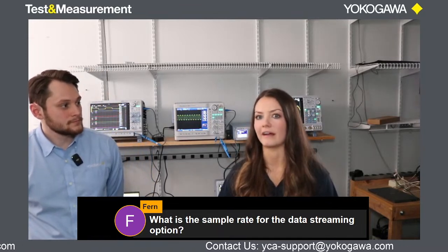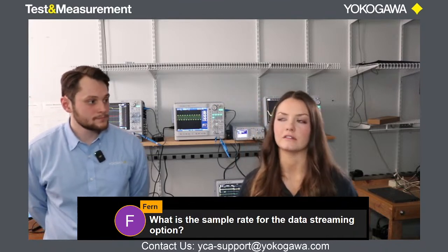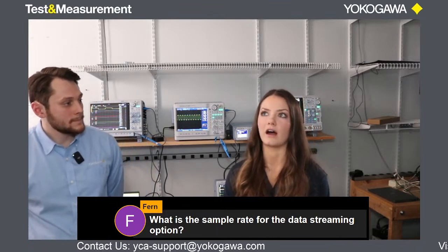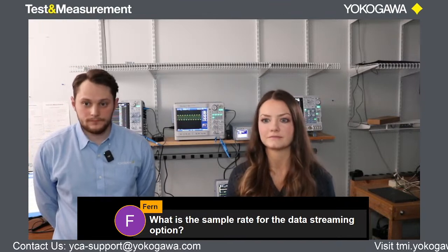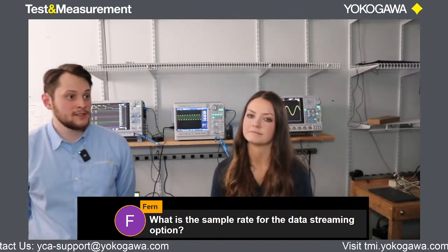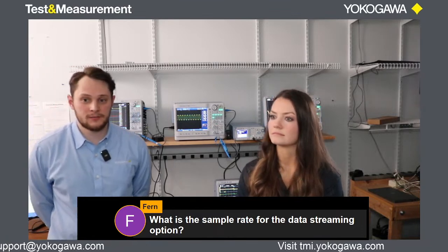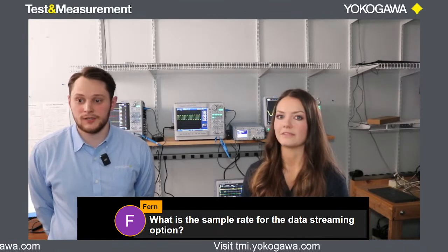So if I wanted just 2 voltages or 2 currents or voltage and current, you can sample at 2 megasamples per second. You can still sample pretty fast with more measurements, but the speed decreases as the channels increase. So it's 2 megasamples per second for one element, because you would be pulling both voltage and current from one element most likely.